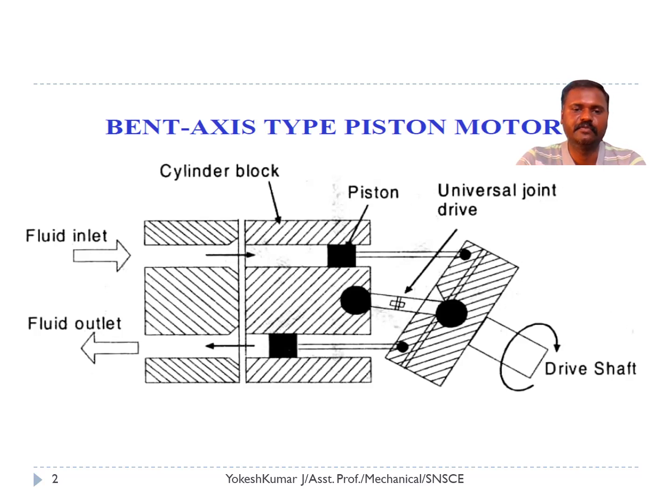When the pressurized fluid enters the stationary cylinder block, which is connected with the rotating cylinder block, the pressurized fluid pushes the piston. The thrust force exerted on the piston will make a linear motion of the piston. The piston will move from left hand side to right hand side. That is, the extension of the piston is accomplished.